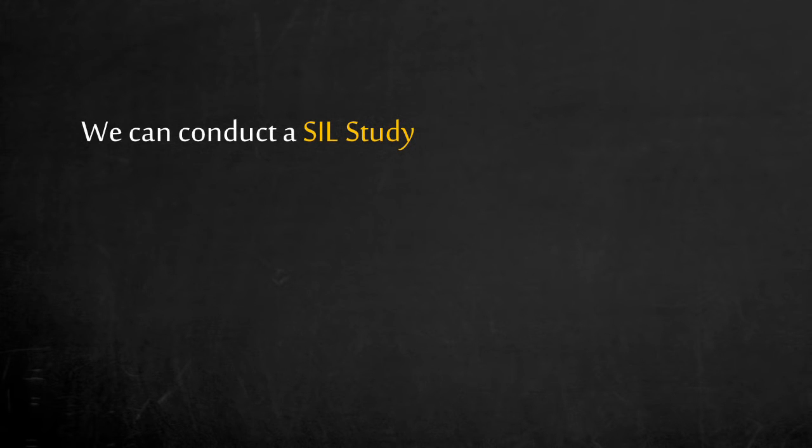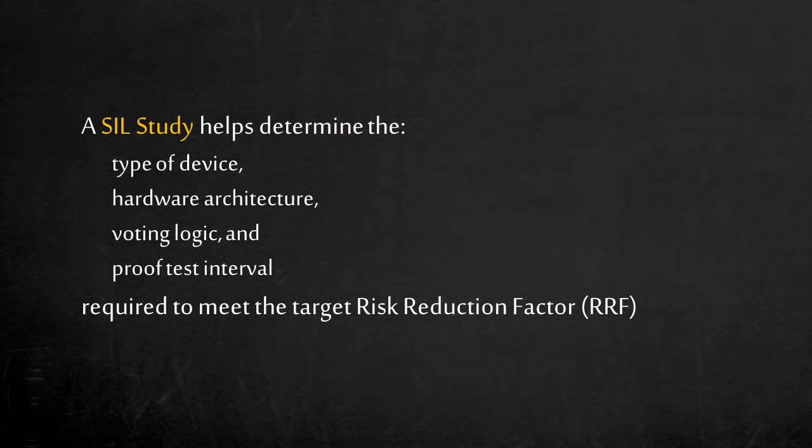We can conduct a SIL study, which is also called a safety integrity level verification in the IEC standards. A SIL study helps make these decisions: the type of device, such as the type of sensors, logic solver, valves, hardware architecture, the level of redundancy, if any.